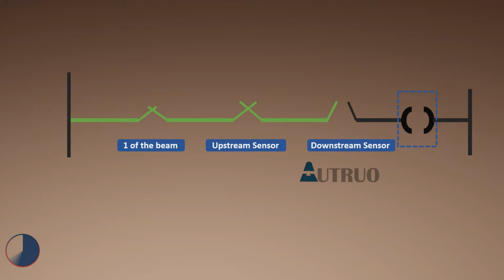So in a nutshell, the pallet will trigger this sensor at the muting inlet. And it will also trigger the other sensor at the outlet. This is also applicable to the other muting system. Again, these activities should not be put in bypass mode in an industrial setting.